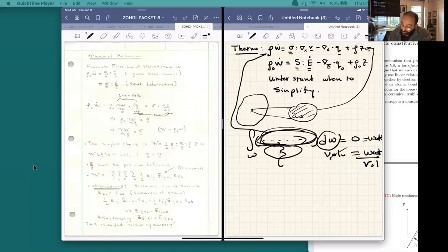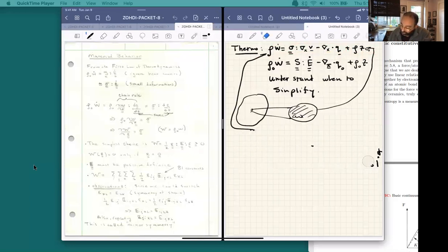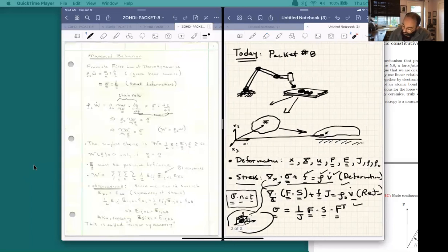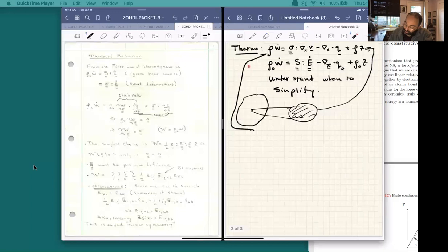By the same token as before, when we look at these kinds of simulations or formulations, oftentimes we'll rewind the movie for the deformed configuration and rewind it back to some initial undeformed configuration, just like before. If we do that, we get a differential equation that looks like this. It is the analog of having the current configuration and the reference configuration formulation for balance of stress. We have the same thing for thermodynamics.